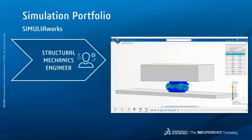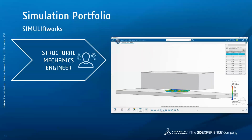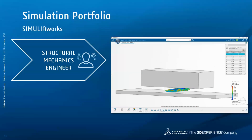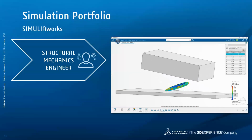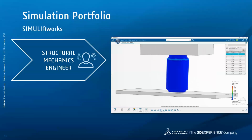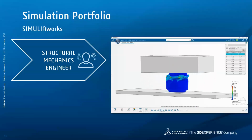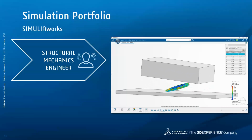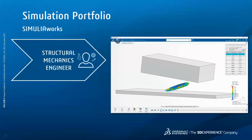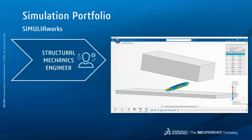You've got all the same expert meshing and post-processing tools, but now you also have access to the material calibration app. For example, if you're analysing a rubber seal and you want to select the best hyperelastic material model, you can take your experimental data, use the material calibration app, and identify what is the best material model for your analyses. And you're also able to restart analyses. So if you want to add a subsequent step after you've got a solve, you can do that. And there's also extra geometry simplification tools.